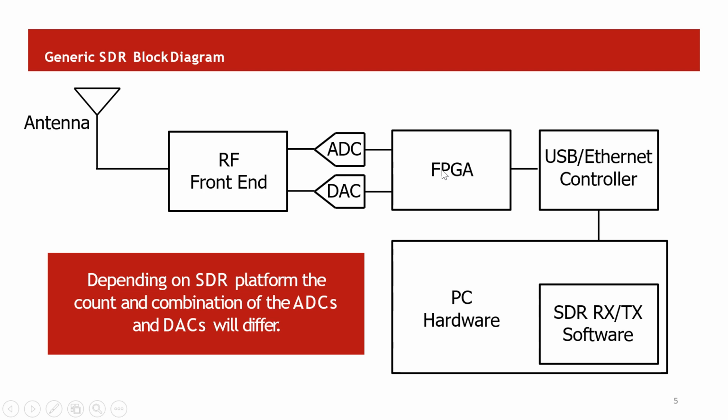The FPGA and the analog to digital and digital to analog converters play a major role in this. The field programmable gate array is basically an integrated circuit which can be configured by the customer. These are not pre-configured as compared to traditional radios, so everything is controlled by software, in which we can configure different types of frequencies and bands.